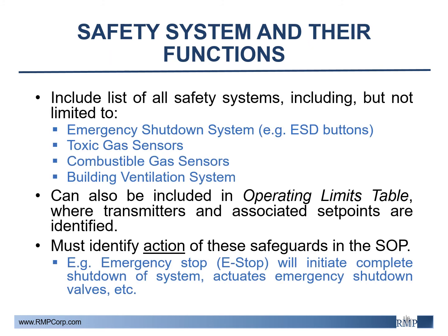A list of all safety systems should be included in the SOP. There are some examples listed in this slide. These can also be included in the operating limits tables to include the transmitters and associated set points. It is most important to identify the action of these safeguards, whether it's an ESD or if it triggers an audible alarm.